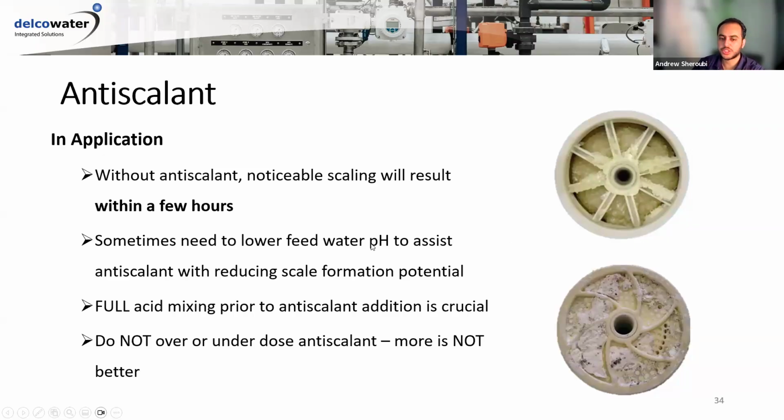But we really haven't had many challenges with pH, any detrimental challenges to operating membranes. And you do not want to overdose this. You need a small amount, and that's it. Actually, a lot of anti-scalant could help biological compounds grow, so then you get biofouling. So it does need to be tweaked. And again, all of this stuff gets tweaked with these systems when they're built and when they're started up.